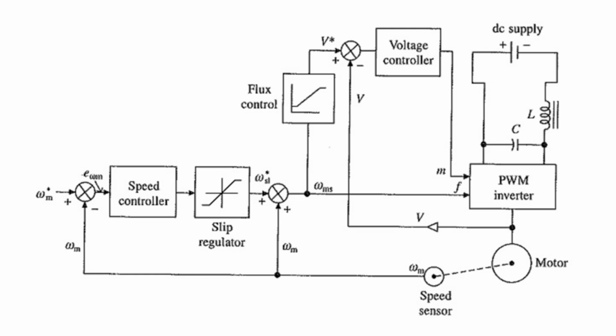Here we have the speed error, which is passed through the speed controller, that is the PI controller. The major advantages are that we can get a good steady state error and attenuate the noise. So the speed error is passed through the speed controller.